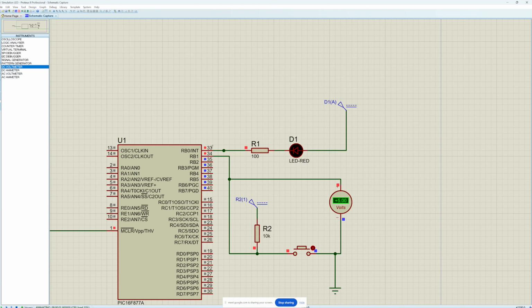The controller got initialized. During and after the initialization, both pins are in high state. RB0 is in high state, that's why the LED is not turning on. RB1 is in high state, which ensures that this pin has enough voltage to monitor the changes.